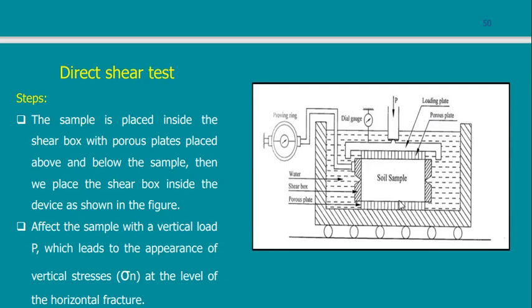The direct shear is a container having a sample, and this sample is put between two rings, an upper ring and a lower ring. Imagine that you have a cylinder, but this cylinder consists of two parts, an upper part and a lower part, and I put my sample inside. Then I push the upper cylinder, what will happen?